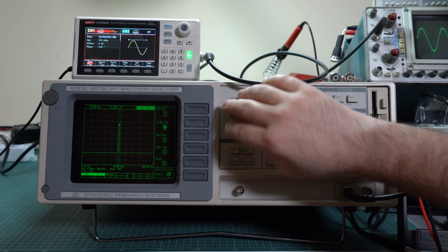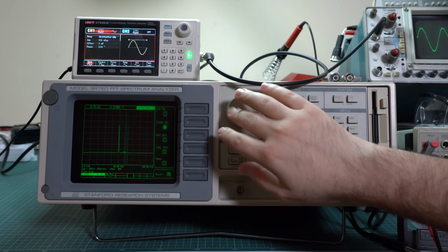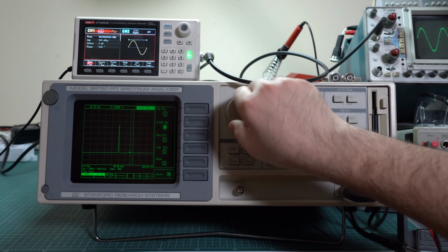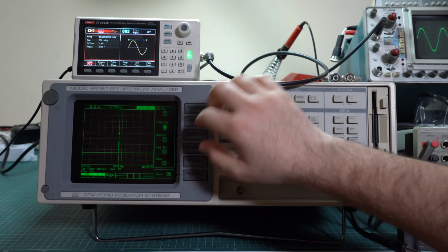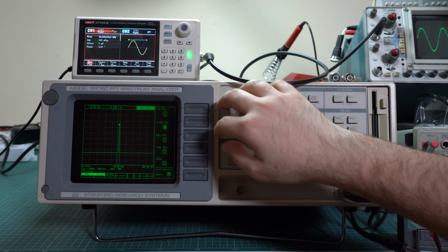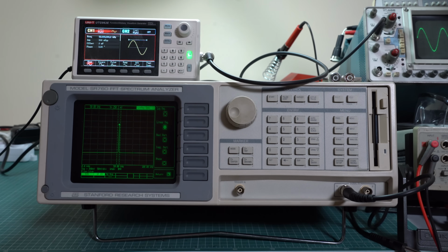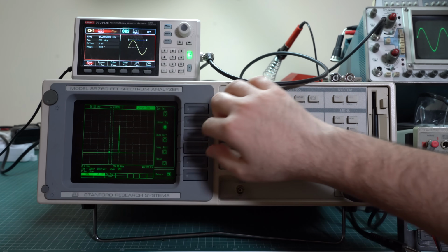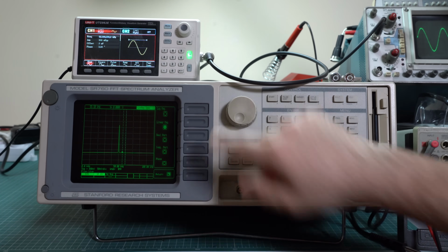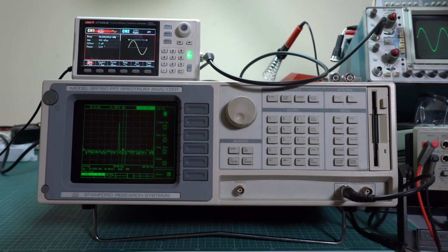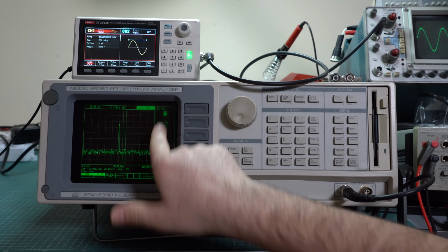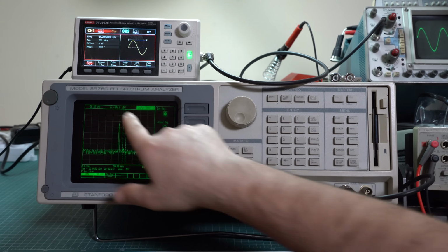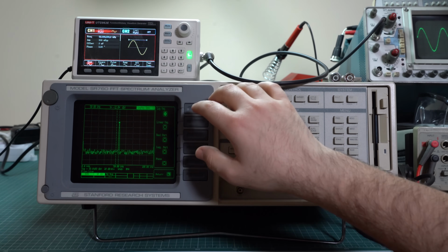But now, since this plot is linear, you don't see the noise anymore, because here the noise has a really low amplitude with respect to our useful signal. So we only get a clean peak. And as you can see, the unit displayed now is in volts instead of dB. In some cases this might be useful, but most of the time this is a logarithmic scale. So you need to go back to the logarithmic magnitude option here. This brings back the noise floor, and this brings back the dB measurement right here.